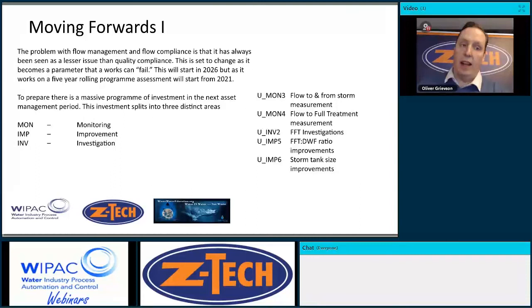and what that can do to both the flow meter and pipe work. I've certainly seen situations where penstocks have been situated far too close to storm weirs, and what happens is the flow channels all the way down the channel, hits the penstock, bounces off, and goes straight down the storm discharge.